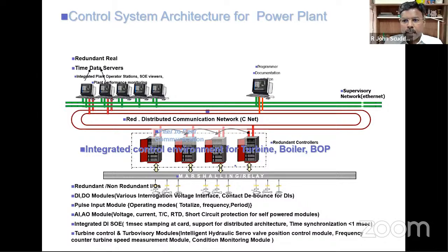The tag which was in 0 state has become 1 state when he pressed it. If you are sitting in the engineering station, you will see that when he had not pressed it, it was in 0 state, and now it has become 1 state. This 1 state of the soft button means that this particular motor has to start. So that input will go into another software function block, which will give an output that goes to the field as a 24-volt DC.